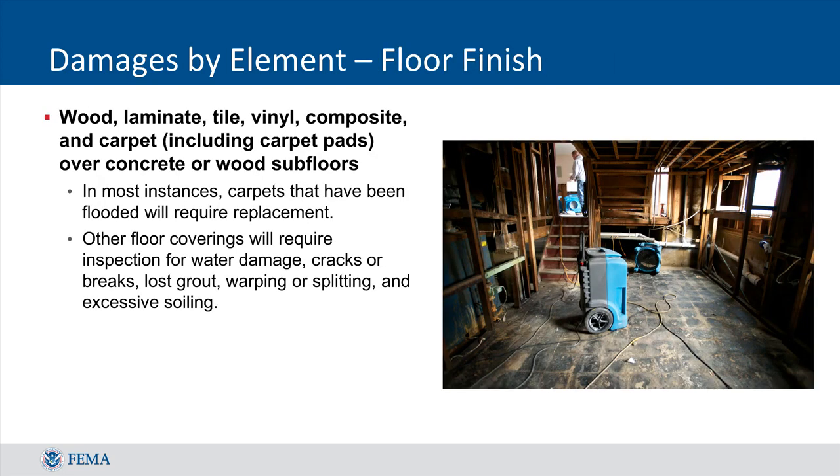Floor finish refers to the interior surface of the floor covering and can come in many different types, including wood, laminate, tile, vinyl, composite, and carpet. As with other elements, you will need to inspect the flooring for cracks, warping, and splitting. In flood events where the depth of flooding is above the first floor, it is common for the entire floor finish to be replaced, especially when the finish is wood, laminate, or carpet. In these cases, you would likely determine that the damage percentage is 100%.